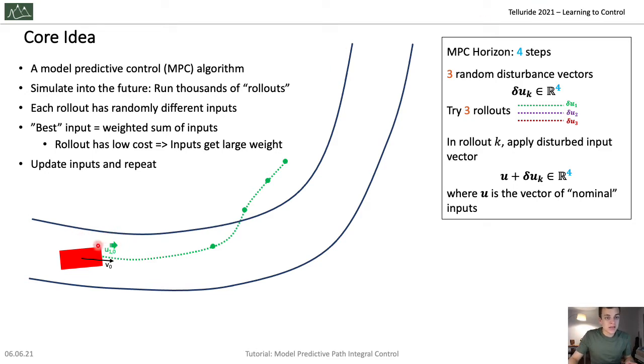So this is the input U of rollout number 1, and index 0, so that's the 0th entry of that vector. Then we land here. In that state, we apply the first entry of the vector of rollout 1, and we land here. Then we do that again for the next entry of that vector and the last entry of that vector. Now we've applied all those inputs and we land in this final state. Over the time of that state evolution, we accrue a cost of 2,000.